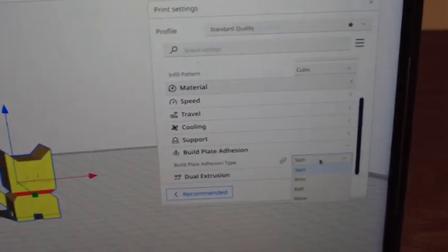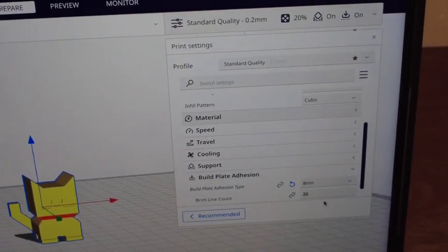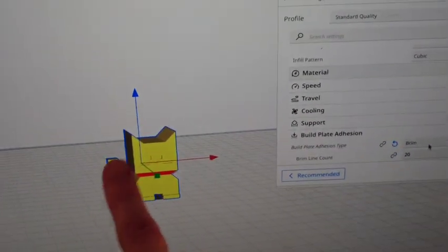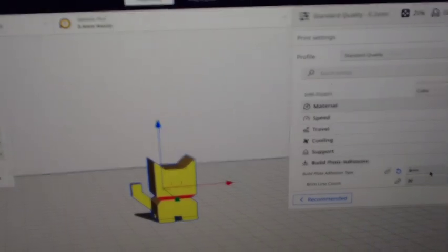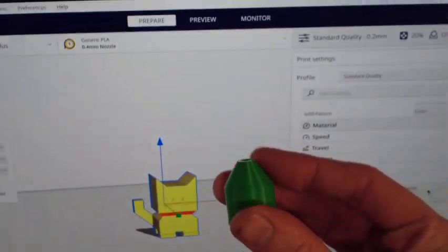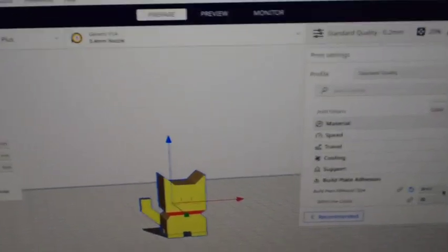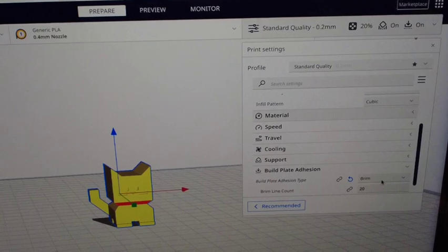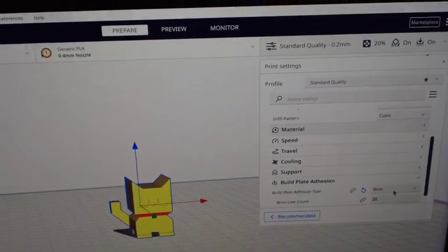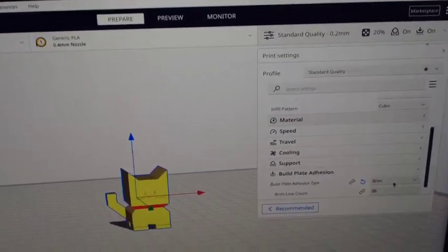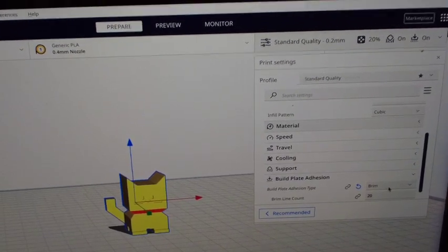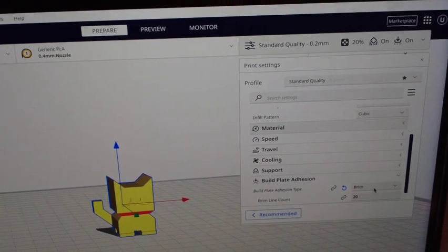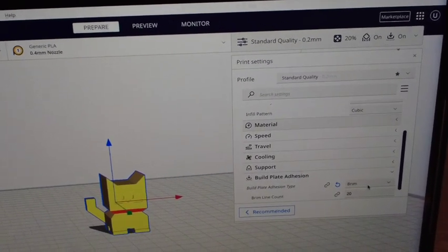The one I like to set is a brim. The brim will give you several layers around the edge and create a little life raft for it, which also helps the item stick to the plate. And again, I think it's a great way to start the print on a continuity of plastic, not straight onto the glass on its own. If there are going to be errors, I always watch the first layers, and you will see if it's not right, and then you can cancel.